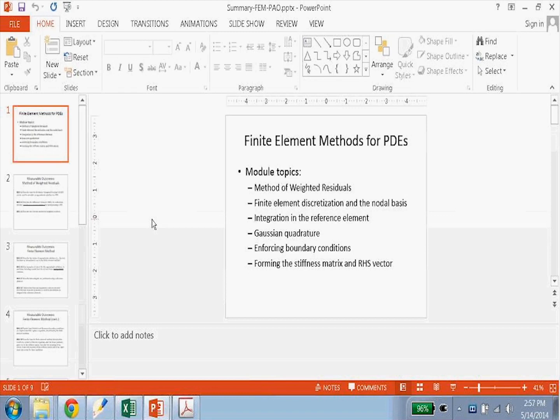And the Jacobian here is just the determinant of this matrix. You remember that? I think you guys must have done this with Bikram. I think I was away this lecture, yeah? So you end up with this J, and this J here is just the determinant of x2 minus x1, x3 minus x1, y2 minus y1, y3 minus y1. So basically this accounts for the change in the area because you're integrating over this element compared to the reference element.